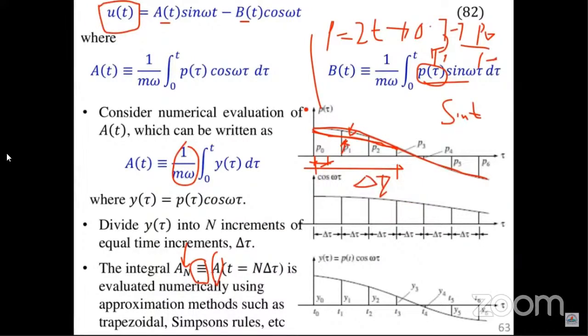Of course, we are not interested in minimum. Maximum is the worst case scenario, so that we know in our design whether the maximum displacement induced by that external applied force is sustainable by our structure, because we know the material characteristic. If it's a concrete structure, a concrete column, will it be able to take in that displacement? Is it allowable in our design, or will the structure fail? If not, what can we do?